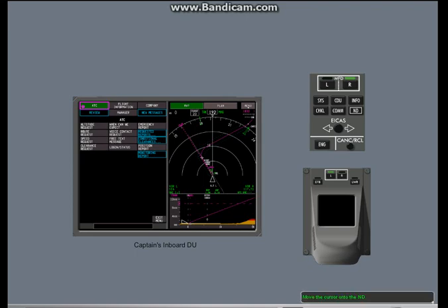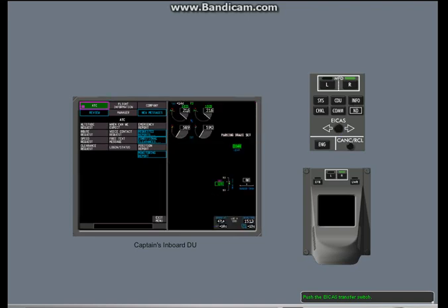You can also move the cursor to the MFD windows with the CCD cursor location switches. Move the cursor onto the ND. The cursor moved onto the ND because you told it to go there. Let's see what occurs if ICAS is moved to an inboard DU window that contains the cursor. Push the ICAS transfer switch. The cursor moves to the other window. The cursor cannot be shown on ICAS.